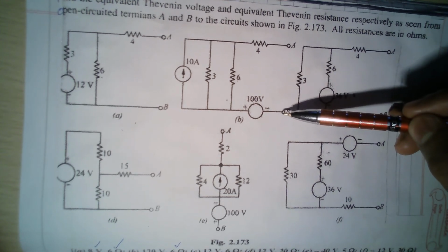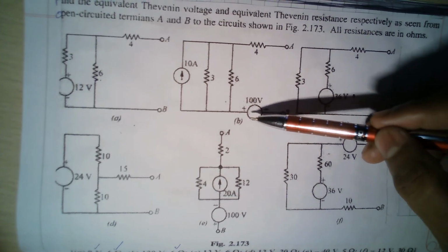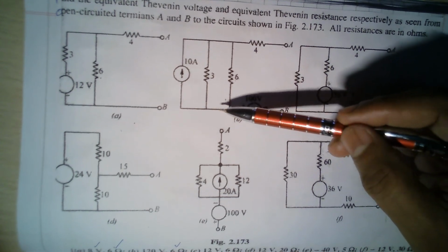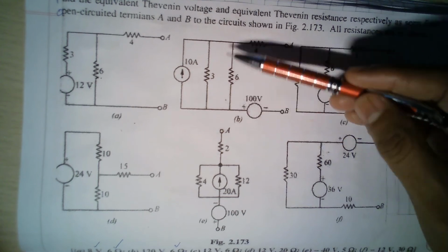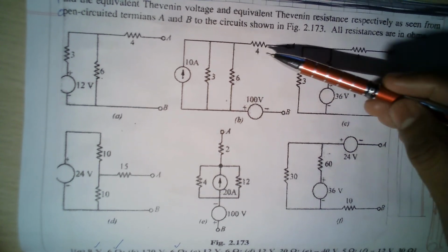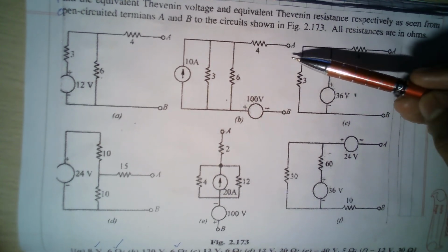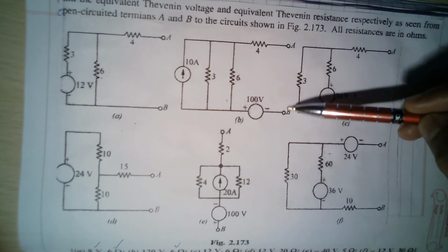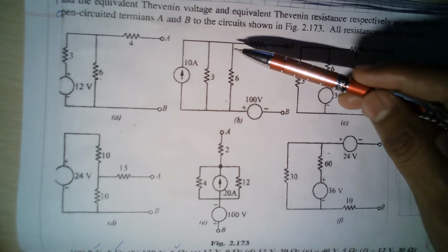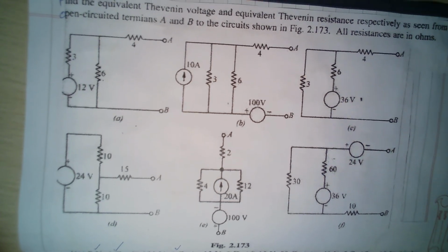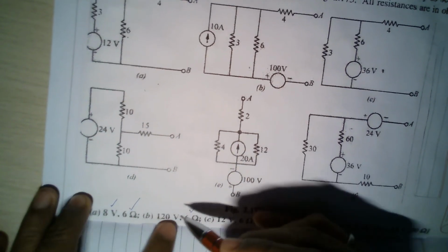KVL from B to A. So from B you go minus side to plus side, you increase by 100 volts. And here I said it is already 20 volts. So increase by 100 volts and increase by 20 volts, so 120 volts. And here the voltage drop is 0. So by the time you come to A, VAB is plus 120. Plus 100 here and plus 20 here. So plus 120. Okay, so that's exactly what we are having here.